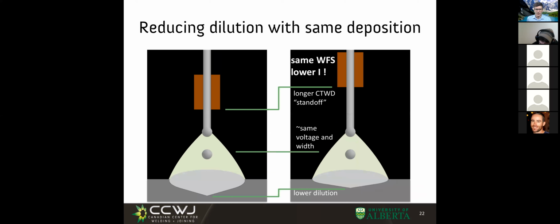Here we have a very interesting problem. I was involved in this. A local company was making overlays. In overlays, you want to add a material to a plate, for example, for wear resistance. But you don't want to dissolve your bottom plate, because the material you put on top is very expensive. And if you start melting the bottom plate, you start mixing all the good material with all the cheap steel, right? So you want to reduce dilution.